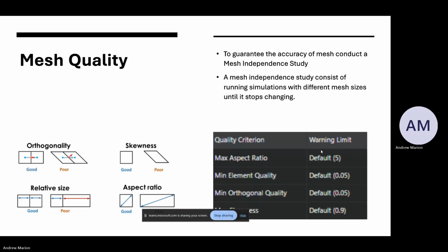For most club work, you might not do mesh independence studies. You just want to make sure you have a relatively high number of cells. If you're using the student version, 1 million cells is your limit. You can't do more than that. To give you a ballpark, in my research lab, where I have the professional license, I typically work with anywhere from 1.7 to 2 to 3 million cells on my research topics. So 1 million is limiting, but not too much.